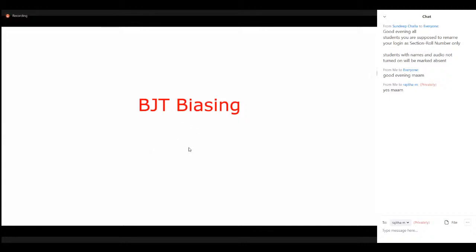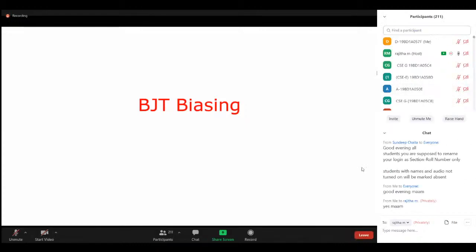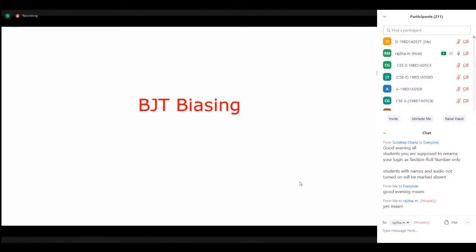Why do we prefer the transistor as an amplifier? In order to amplify the weakest signals, which have low strength in voltage magnitude. Those signals are applied as an input signal to the amplifier stage, so the voltage level is amplified at the output of your amplifier. In an amplifier, we utilize a component termed a transistor, the BJT or bipolar junction transistor, and it must be operated in the active region.